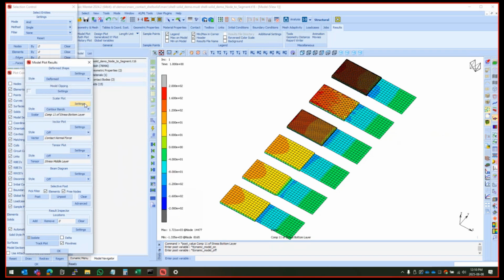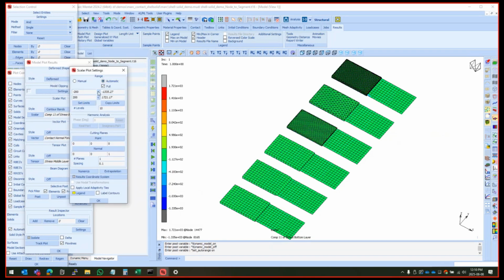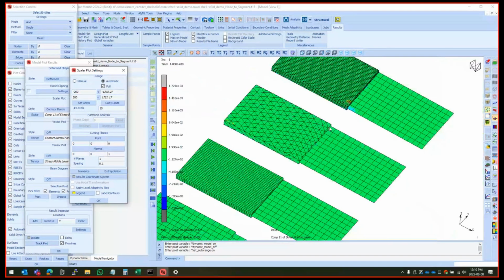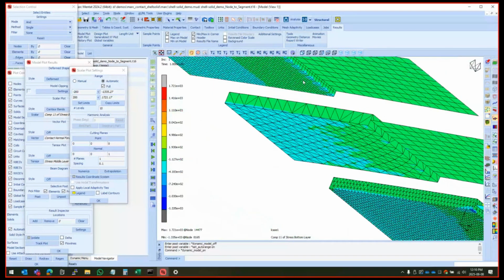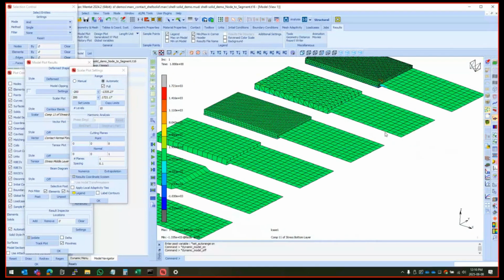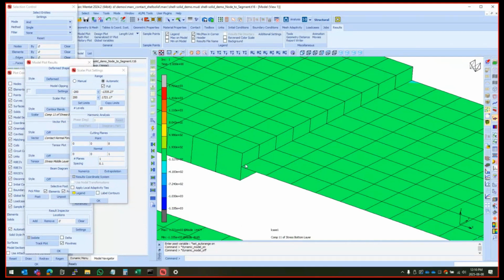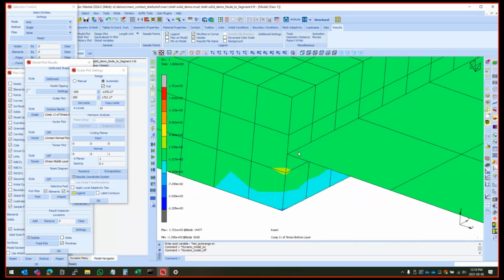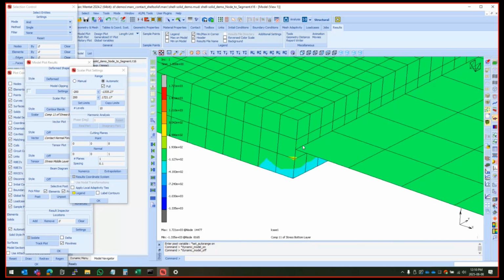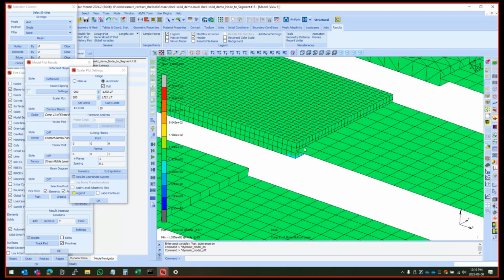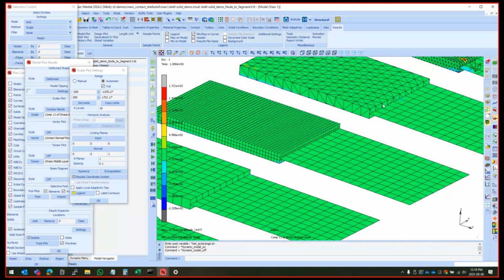Now the problem was we've seen insane stresses of the order of gigapascals in that, and even in this model, we see pretty large stresses over there. Now the question is why? If you go back to the whole argument about nodes making contact to faces, that node effectively makes contact to that whole face. If I zoom into this one, in theory, that one makes contact to this face. That one makes contact to these two faces. They don't make contact to that section because, well, the mesh is finer. So that finer mesh already messes up pretty much everything in the result.